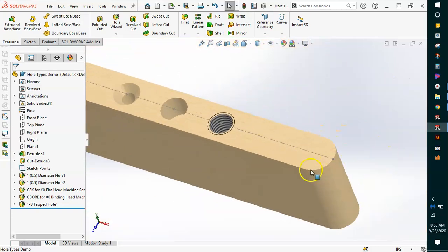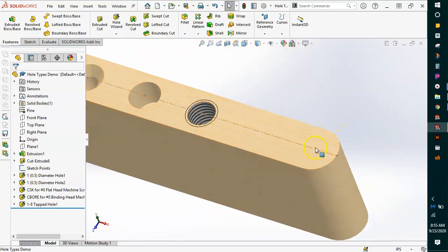Okay, so down here in this empty spot, we're going to be putting in 2 more holes. One of them I'm going to show you how to do a flat bottom. One I'm going to show you how to actually do real threads, so you can see the difference between the cosmetic and the real threads. And I'm also going to show you how you can edit a sketch or edit the placement of these holes if you don't already have these dots like I gave you.